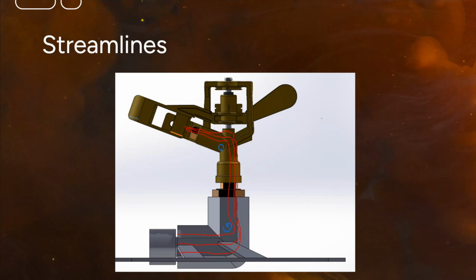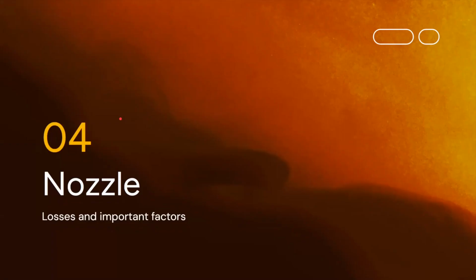If we do not assume the flow to be inviscid, there are possible losses and separation in the bends, as shown here and here. As you can see, they curve to the outside of the bend. However, the piping has a small diameter, which should limit the formation of large separation zones and formation of vorticity and eddies here. Due to the small diameter, turning vanes would also not be practical for limiting these losses. So now we move on to the nozzle.